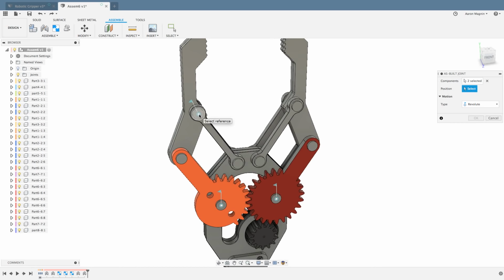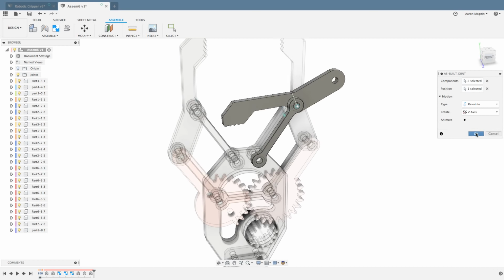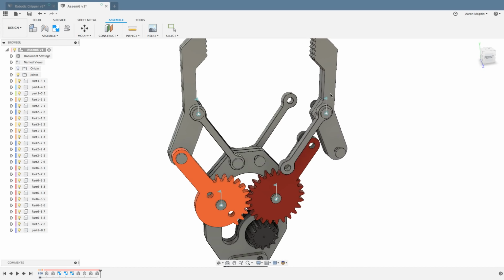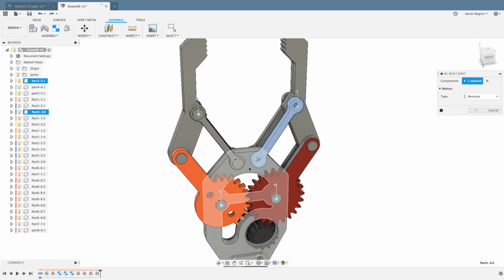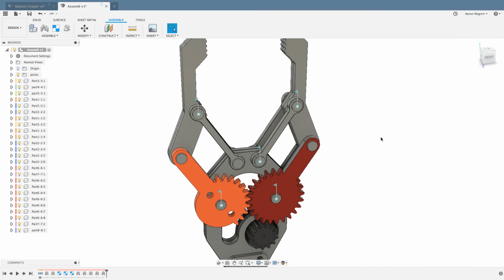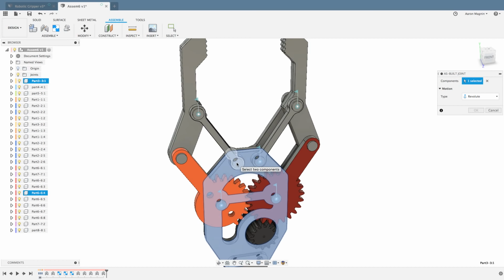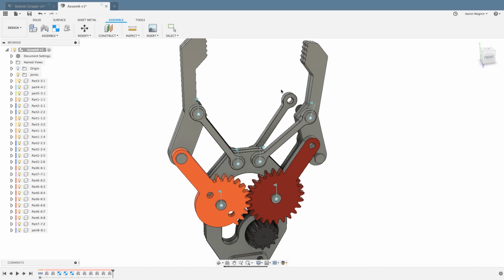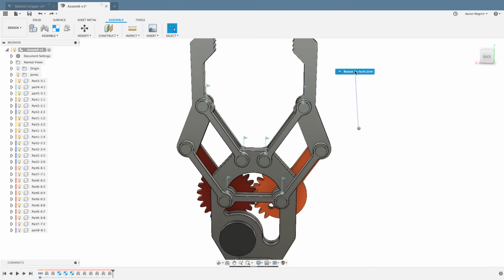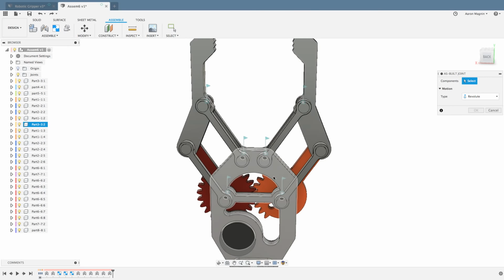Let's go ahead and just continue on. In this case, we'll add another revolute there, repeat our as-built, and continue along a little bit further here. So, we're getting a little bit closer. We're obviously missing some more of these joints, so just continue on. Click and check. That's kind of my mantra that I adhere to. Oh, not the correct part once again. So let's go back to the linkage and maybe the pin and define some more of this rotation. So we're getting closer. We're getting closer every second here. We just need to kind of continue with these as-built joints all over the place.